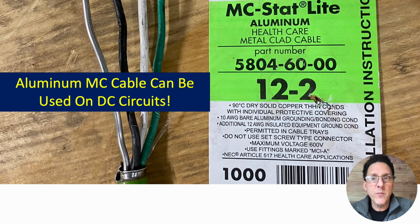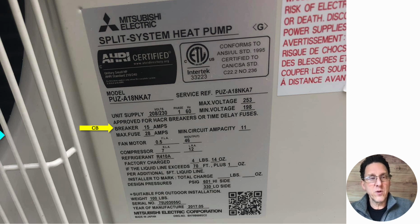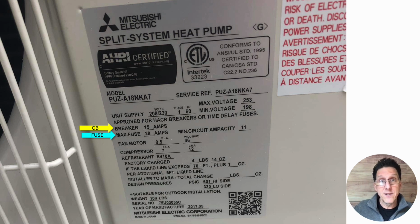Let's take a look at some other equipment. This is a nameplate information for a heat pump. Now, it says maximum breaker size, 15. Well, what if I want to use fuses? Well, then it says maximum fuse size, 28. 28 is not a standard size. 30 is, but you can't go to 30 because it says maximum fuse size, 28. You could put a 25 or a 20. You can go smaller. If it doesn't trip or blow the fuse, you can put a 20 amp fuse there, but you can't put a 20 amp breaker in.